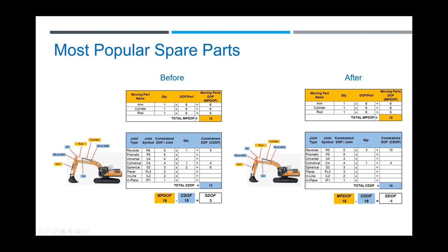Even though you have extra degrees of freedom, it still works fine, even if parts are bending and things like that. But then the next series, they decided to go back and change the spherical joint to a hinge joint in the front and change it in the back. So they went from a 3 degrees of freedom mechanism to a -1.